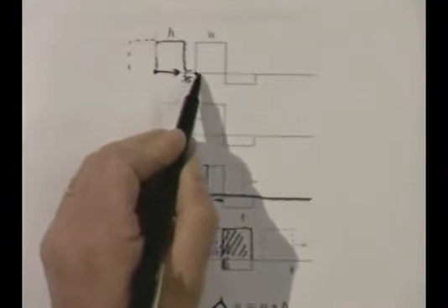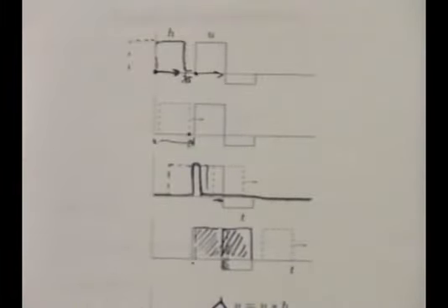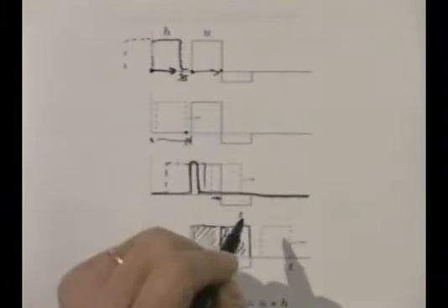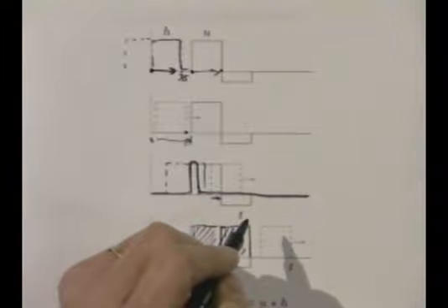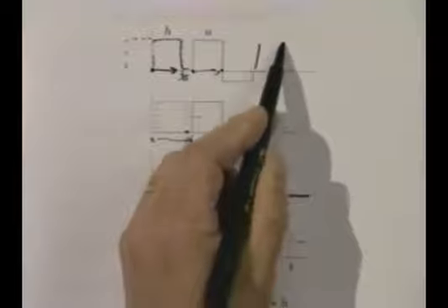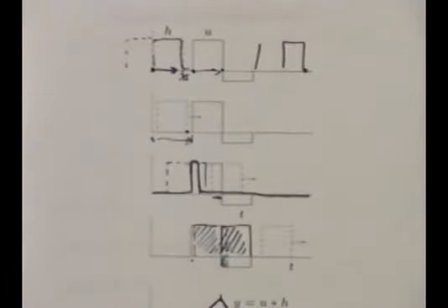As time goes along here, I'm averaging the last 0.75 seconds of the signal, and it's rising. And I get my highest number about right here or something like that. It's also clear that once this thing has passed over here, like at this time, the output is again 0, because the average over the last 0.75 seconds is 0. Because the input has been silent for 0.75 seconds.